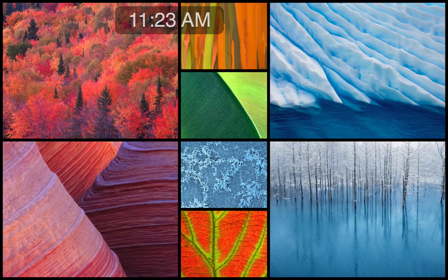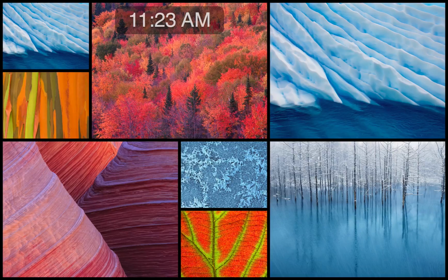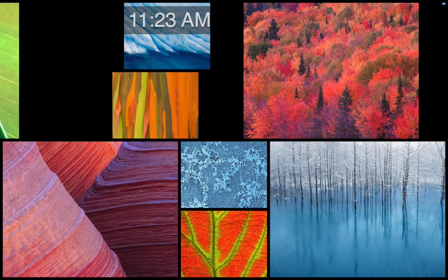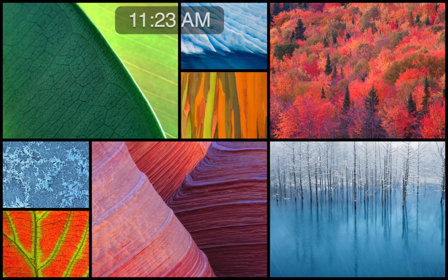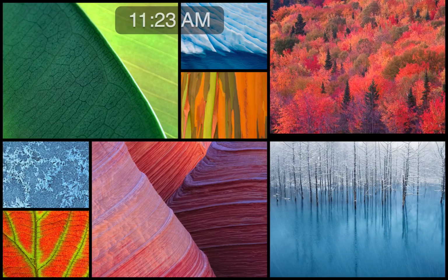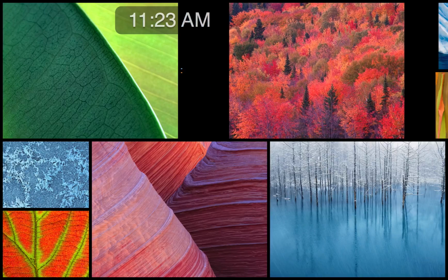And my reference planes, I want to make sure those are right on. So this wall actually needs to go way up here to the other side of this reference plane. Okay, so I'm gonna just delete all these other guys because they're all wrong, and it's so much slower to move them individually. It's so much faster just to get one right and then array it.